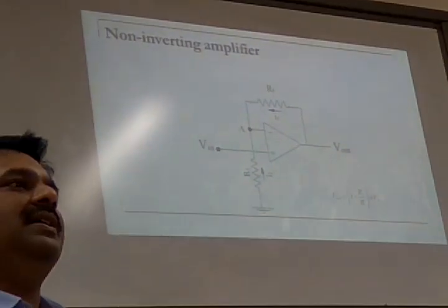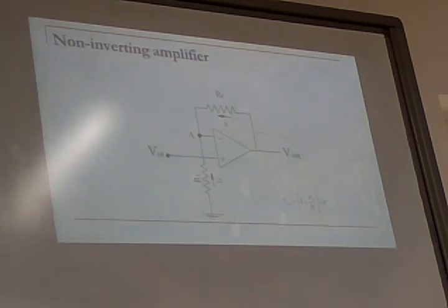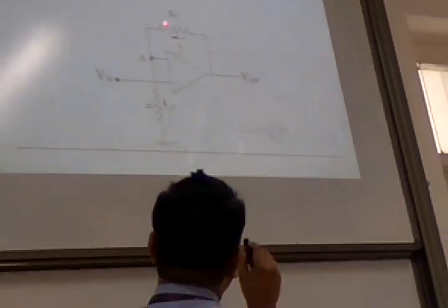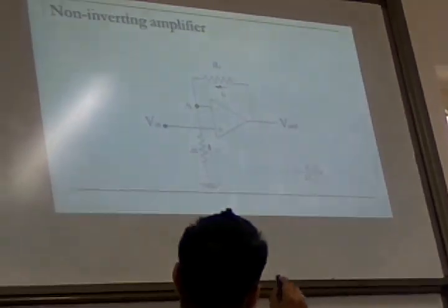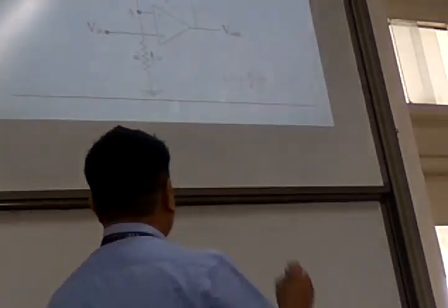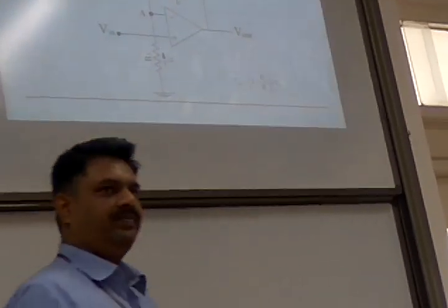Here the expression for output voltage is given by this. It is R2. Okay, there is a printing mistake, made by me. This is R2. Or here you change it to R1. Anyone, change yours, because that refers to the feedback resistance. It is 1 plus R2 divided by R1 into V.